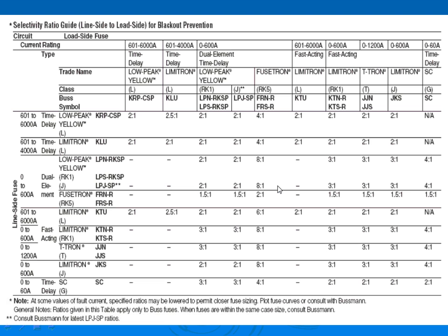Okay, now if you don't have this fancy stuff, I always say, guys, if you don't have fancy circuit breaker software, and you maintain the ratio 2:1 on your circuit breakers, you're good. Meaning, if your main is 100, the largest branch circuit is 50. If you maintain this, you maintain a good coordination. A 2:1 ratio, meaning the main is going to be twice as much as the largest branch circuit.